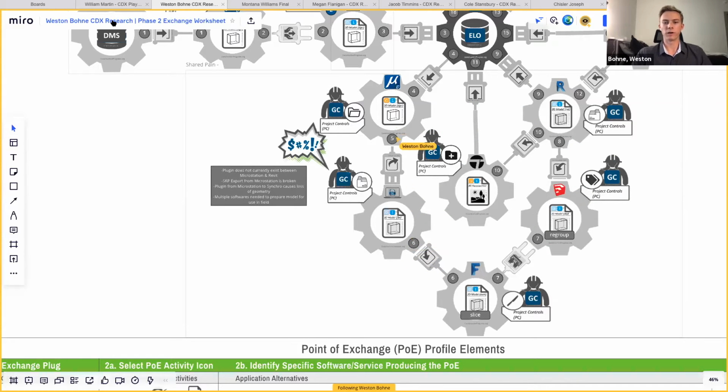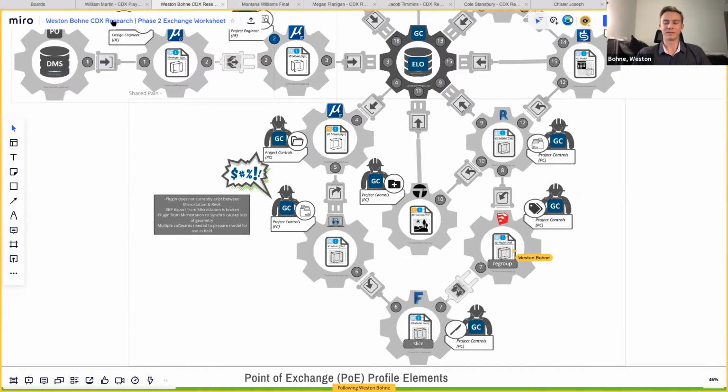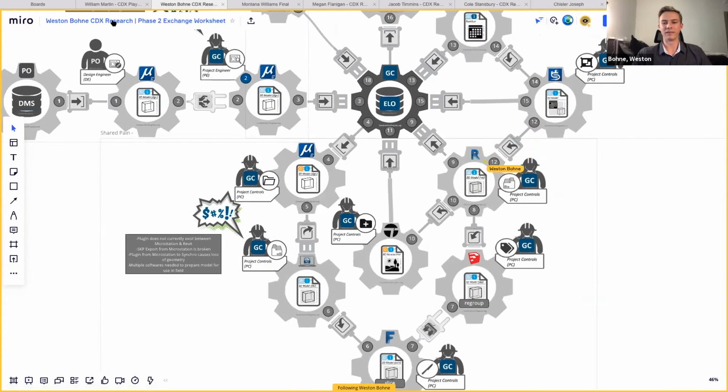So it has to be exported as an FBX file and then brought into Format where it's broken down into the components and then individually exported and reassembled in SketchUp, where each component is then broken down even further into usable pieces, and then finally gets to Revit and then Twinmotion where it's used for visualization.